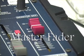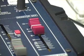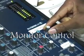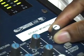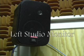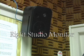This is the master fader. It needs to stay at 0 decibels and should not be touched. This is where you adjust the level of the monitors playing into the stereo. Once it is at a comfortable level, leave it for the duration of your show. You should never have the monitors up loud, as a courtesy to our neighbors at WTMD. Keep in mind that everything you hear in the monitors is what the audience hears in their speakers.